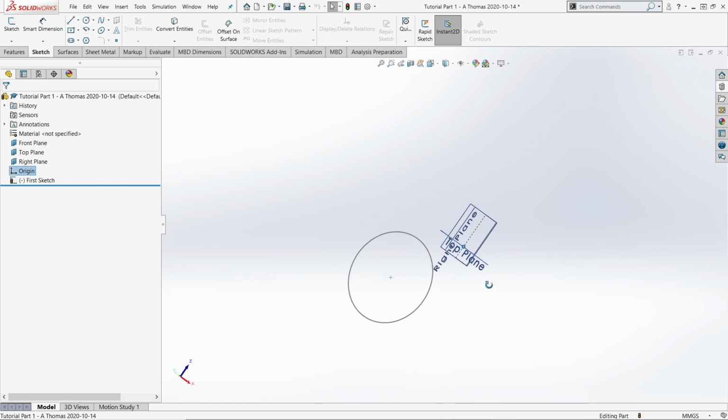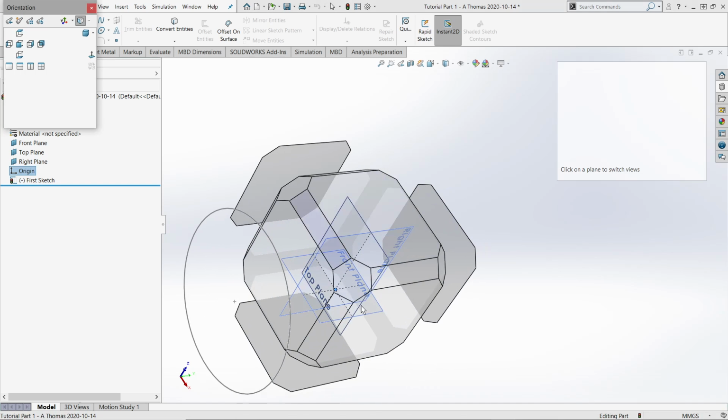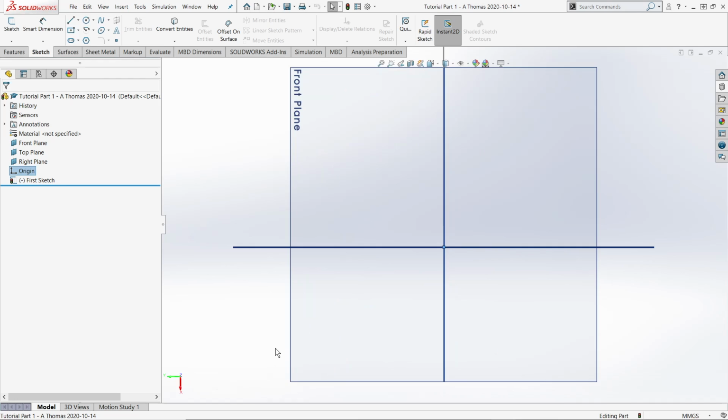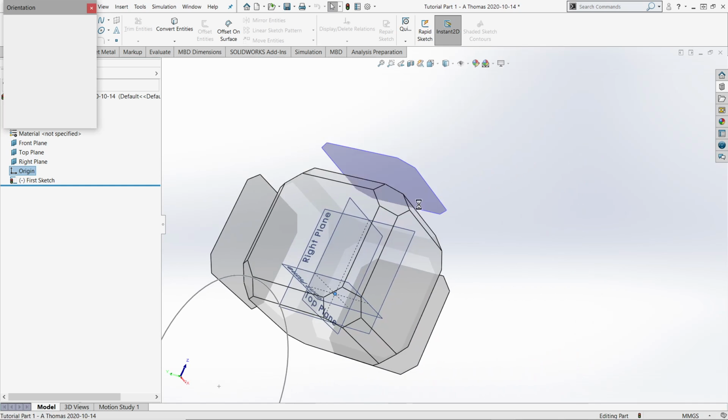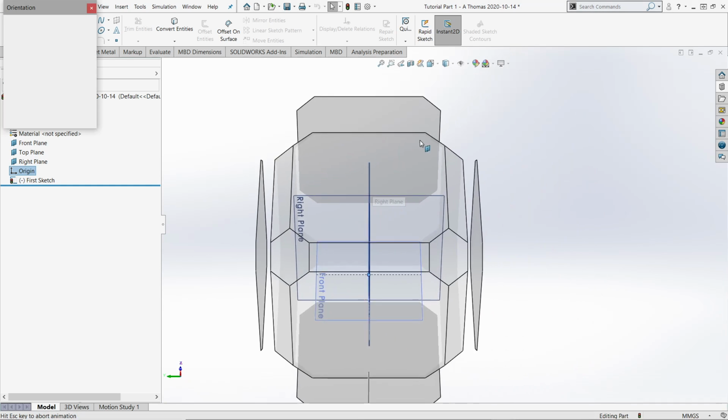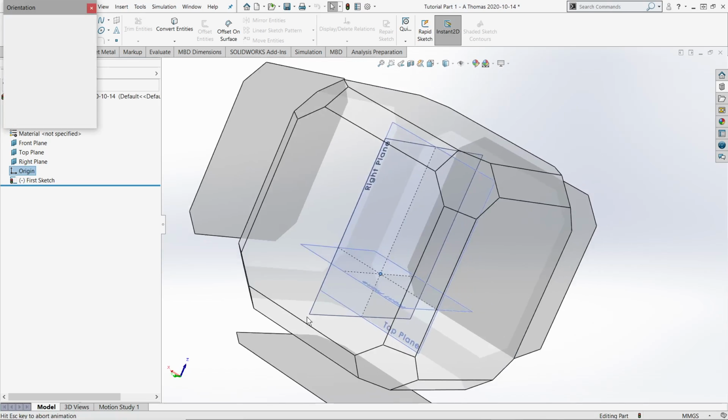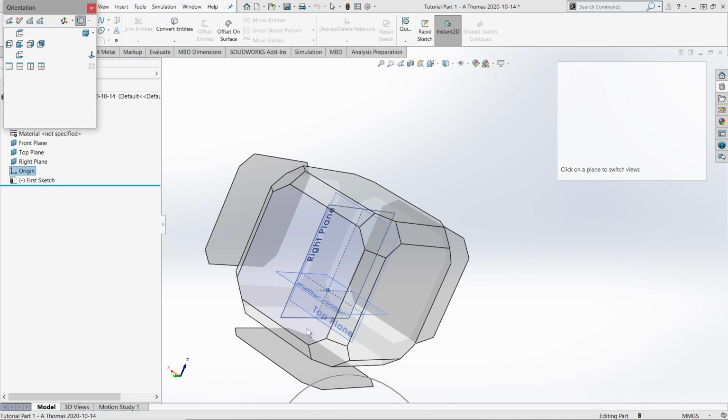But sometimes you can't line it up perfectly, or you get confused and you don't know what you're looking at. And the way to deal with that in SolidWorks, which is really nice, is you hit the spacebar, and it opens up this little orientation cube type thing. And if you click on the face of this cube structure, or these floating faces, it will orient you in that direction. So that was kind of fast. If I click this corner, for example, it'll rotate it to let me see from that direction. It'll make more sense once we have an actual 3D part to look at.